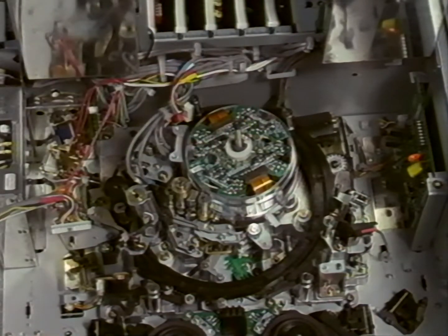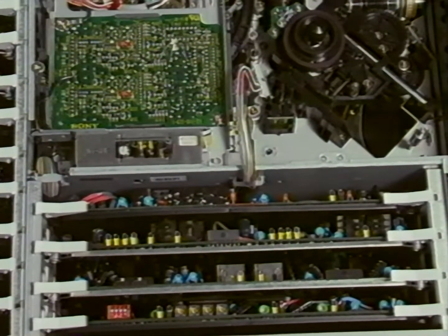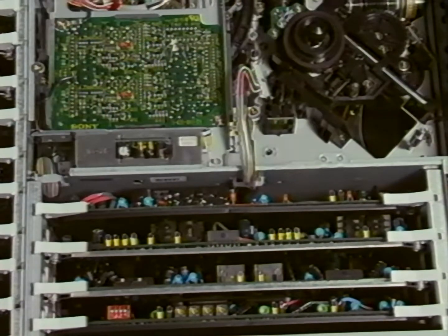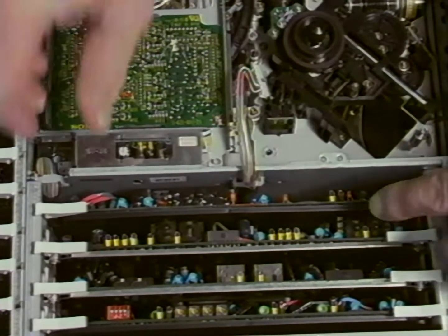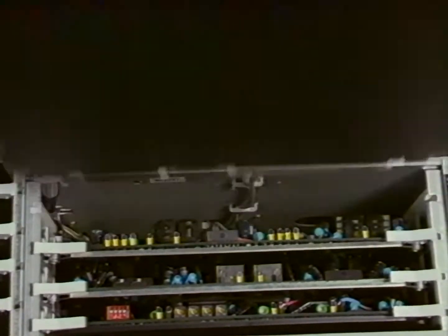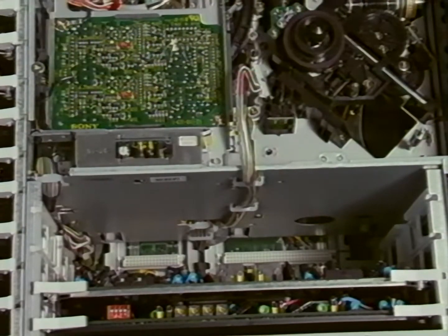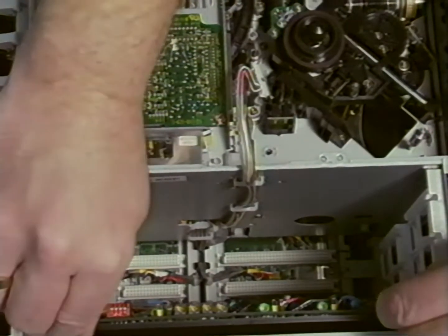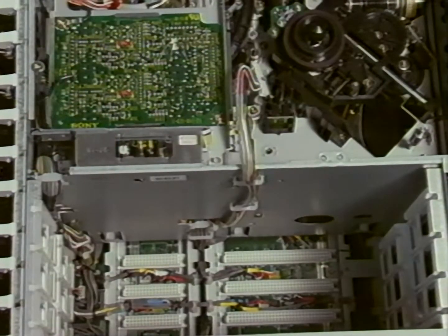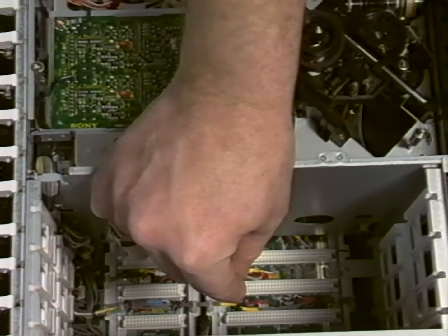Now everything on the top of the drum is clear. The next step would be to remove the 4 connectors on the motherboard, MB116, located between the DEC 42 and DM56 boards. These 4 connectors are CN114, 115, 116, and 117. Also remove the retaining clip to loosen the wires so that they can be fed through the chassis.